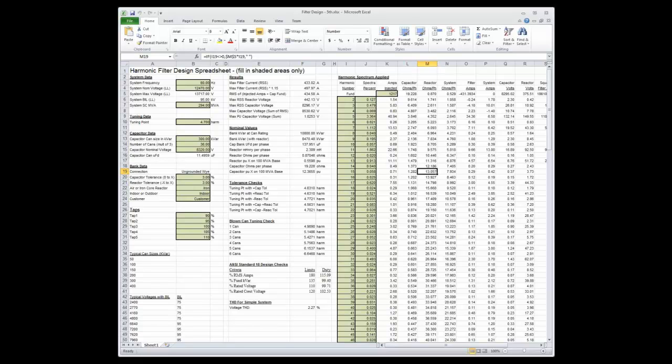And the only switches that I'm aware of in capacitor filter banks are going to be a switch for grounding. In other words, you're in an energized condition, then it goes to a middle condition where it's not connected to anything, and then you ground it for safety reasons. You have to have a real upstream breaker to open and close your filter.